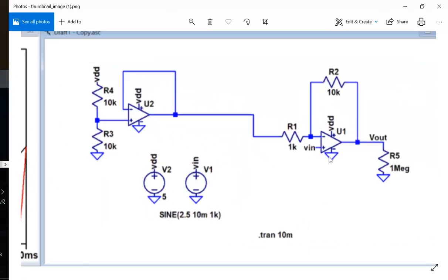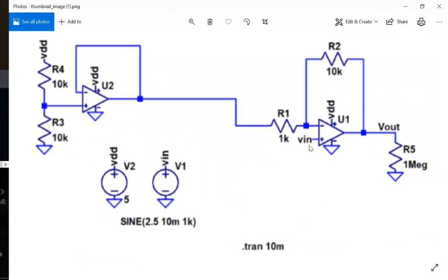Okay, so if you have the Vin going to the non-inverting terminal, again, you need negative feedback, right? So that's the resistor network providing the gain. And you are not grounding this guy. You need to lift it because you are grounding the bottom rail. You are lifting Vin. I'm using 5 volts, that's why I'm lifting the sine wave, the Vin, to 2.5 volts as a DC offset, so it swings around 50% of the two rails.